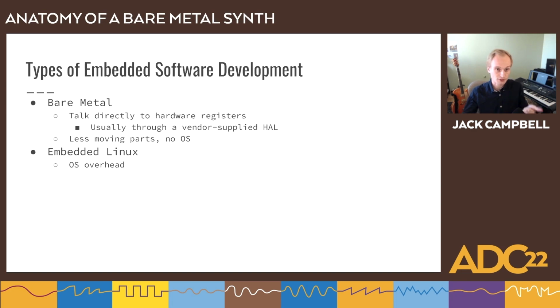So you've got the OS overhead, not only the runtime overhead, but also the learning overhead and having to build Linux from scratch. Talking directly to the hardware is a little bit less direct than in bare metal. You can write drivers and include them in your Linux distribution, or you can use the device tree to interact with the hardware more directly. But there's more to do than just literally writing to a register.